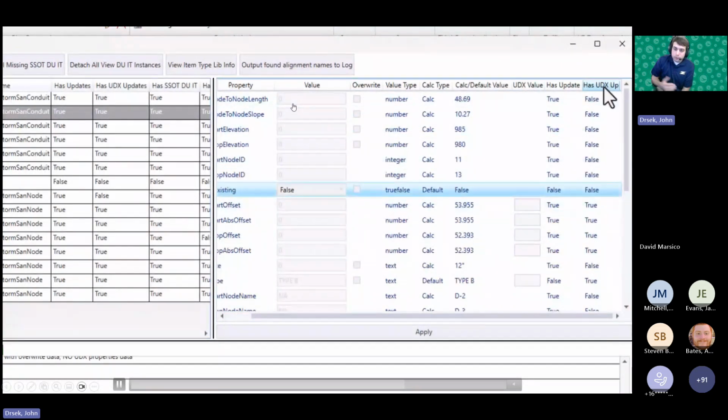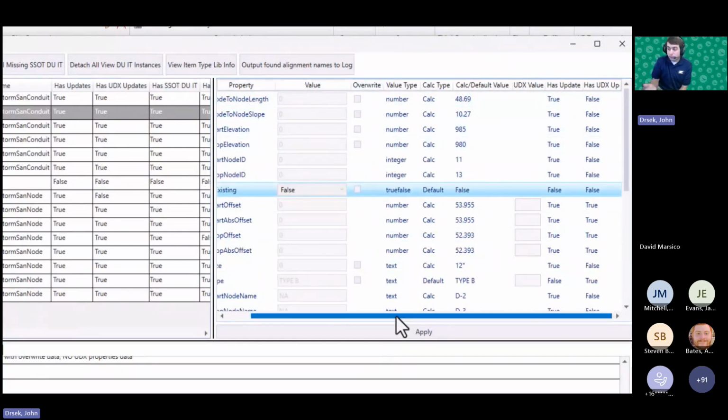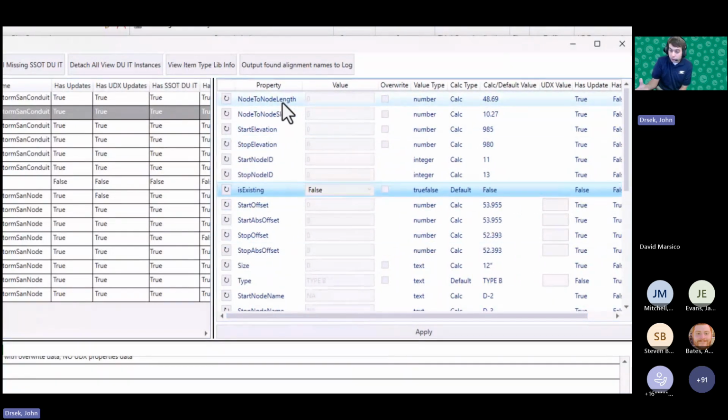Now, I think the biggest example of this is if you wanted to use the head wall. So just have one generic head wall feature, and then replace that parametric cell with the actual head wall. Well, all the type data is on that generic head wall feature, so I can't really default what type of head wall it is. That would be an example where you might want to override that.